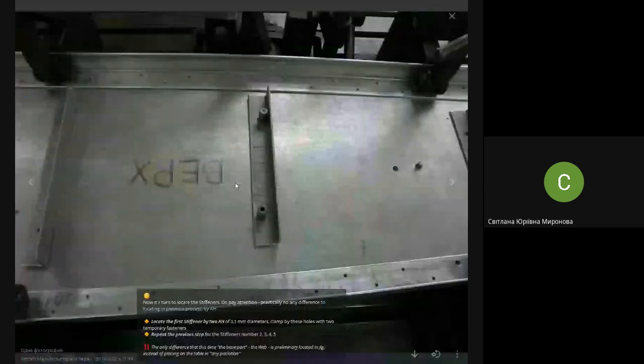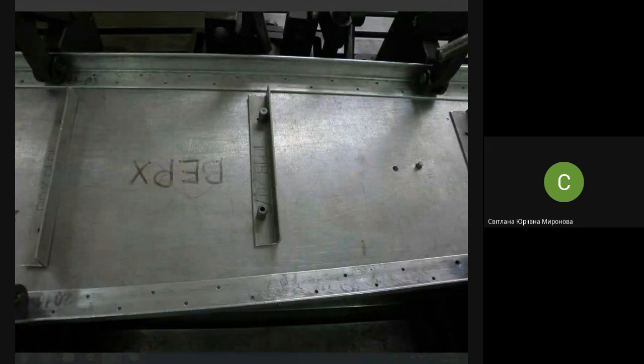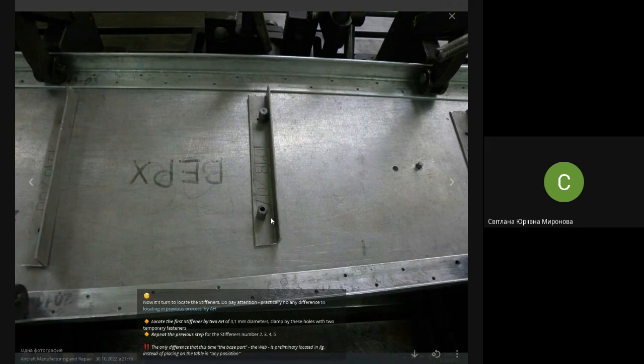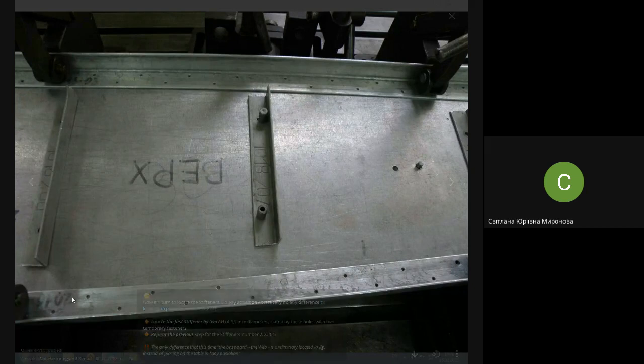About assembly holes, I already said that the stiffener would be located by assembly holes because we have no high demands on accuracy. Pay attention that now all parts together show where to drill holes. Pilot holes show drill here, but pilot holes are smaller in diameter than assembly holes, in order not to mix them up.